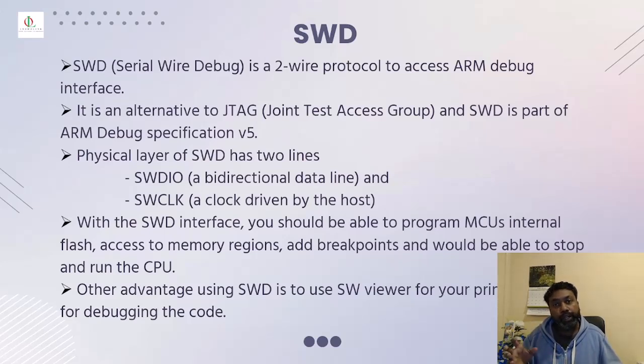The other advantage of using SWD is you can do debug options with printf, meaning with console outputs. If you want to see your output in the console rather than on the actual target board, you can see it in the console window. So that's where SW is really handy to have. Thank you to ARM for introducing such an easy tool. It is very easy and cool when you get to programming. It's all very, very exciting.